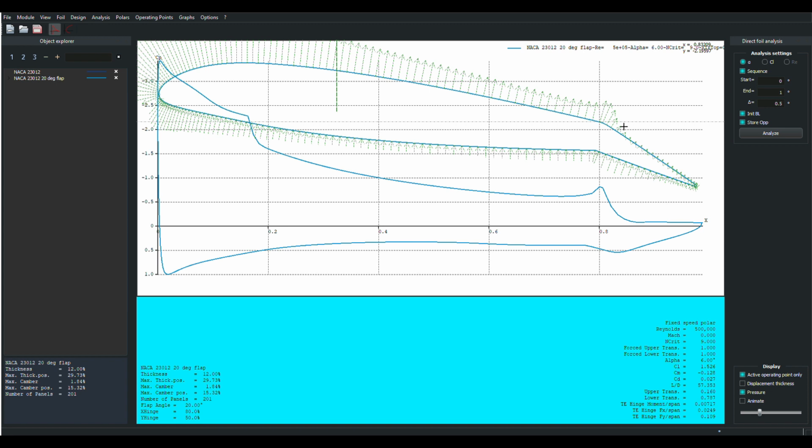Now, sometimes we can work around this problem by turbulating the flow and pulling energy out of the free stream and putting it in the boundary layer as a turbulent boundary layer to help it get through this barrier. And when I went out and tested the various trip strips, I found that the vortex generators helped a little bit. But we have to remember, we're starting out with really slow flow to start with, only 20 miles an hour. And the mass of the air is the mass of the air. We can't change that much. So it's only got a certain amount of energy, and we've spent most of it by the time we get back here. So it still has a hard time getting through here.